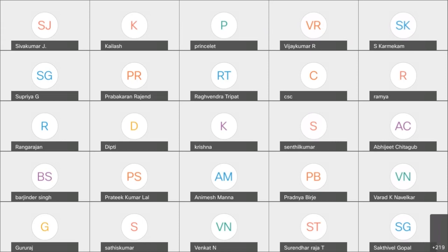And in my project, if I want to reduce this SPFM, I mean, increase this SPFM, in what ways can I try, if I have taken care of diagnostics and all the software implementation and other things? Yeah. Basically, it all depends on the capability of the safety mechanism, which can detect a percentage, right? So one thing is, yes, you can increase the diagnostic capability of your system for each level you identified, and that will help you to increase your SPFM value.